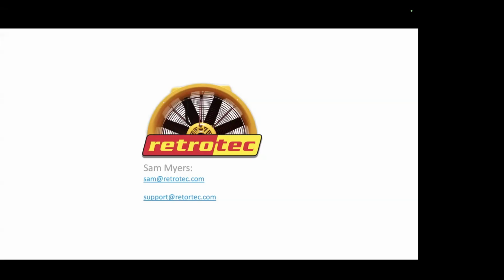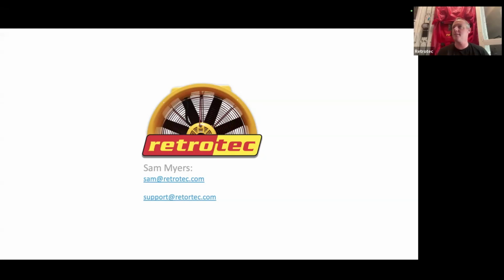So last two, and then I'll call it. Can we talk about ERVs? How does it interfere with the blower door test if it's open outside, not sealed? Most standards, if it's a continuous ventilation method, will allow you to seal things for tests. So hopefully it's in a location where it can be sealed, but that's my recommendation personally. I don't know about you, Sam. Yeah, ResNet 380 will let you tape it off if it runs continuously.